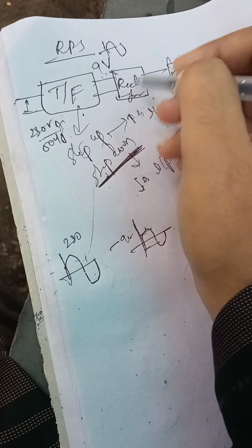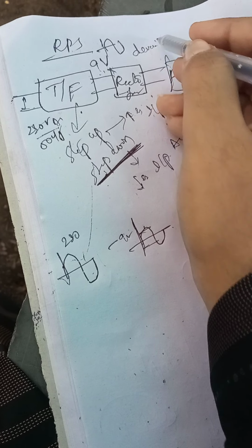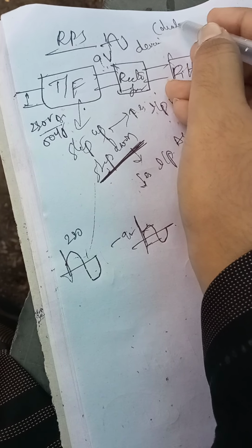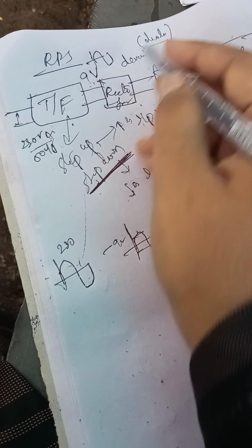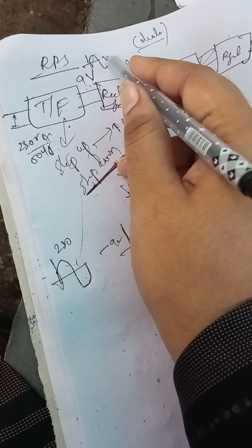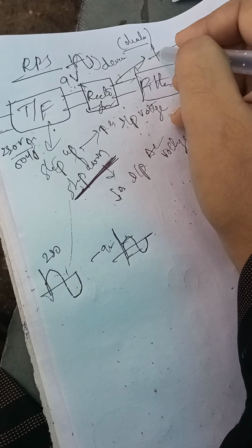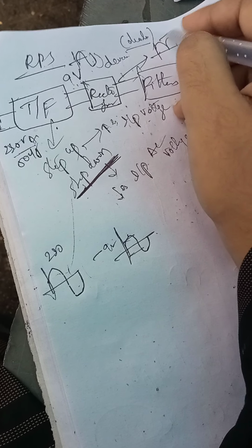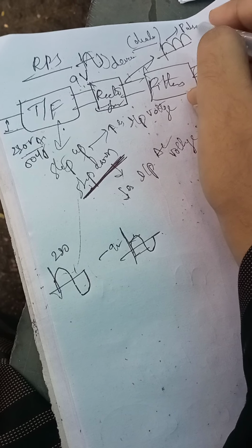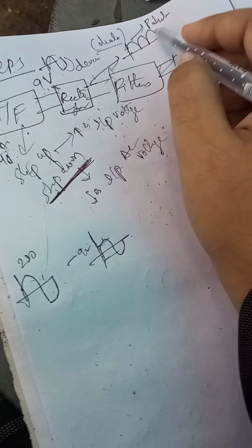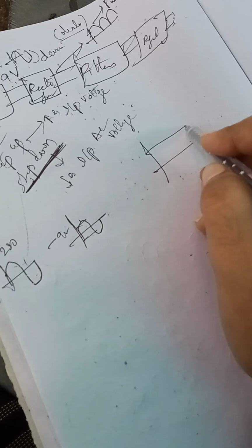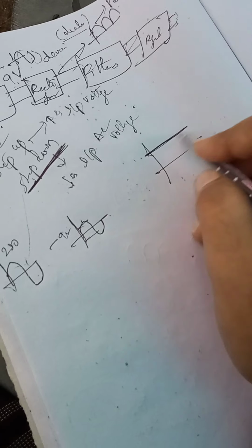Which particular electronic device acts as a rectifier circuit? It is nothing but diodes. So a diode is an electronic device. It converts the bidirectional AC to unidirectional, or nothing but pulsating DC. Pulsating DC. So here, do we get pure DC? No, we do not get pure DC here. Pure DC should not vary with respect to time. There should not be any fluctuations in the magnitude.